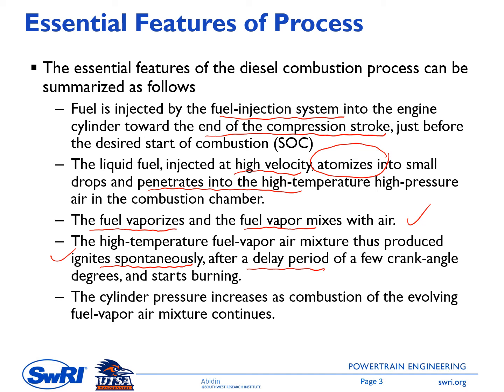So this delay period is the period between the start of injection and the start of the combustion. Then once a spontaneous ignition occurs, it will be followed by a further combustion process. There will be a release of heat from the combustion process, and then the cylinder pressure increases. And then the combustion process will continue consuming the remaining fuel inside the cylinder chamber.